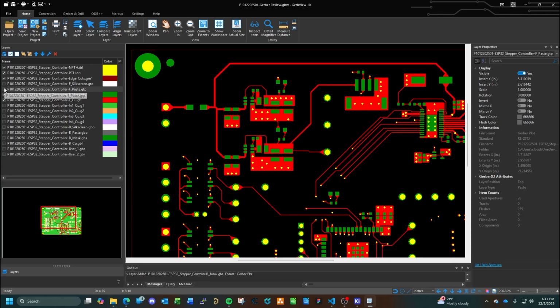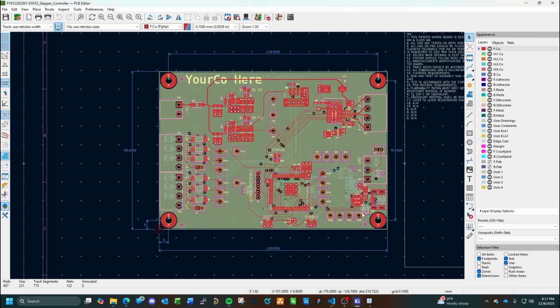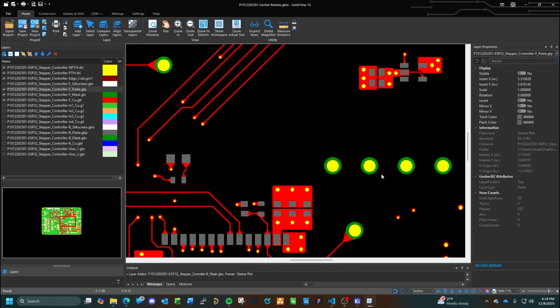And then they line up: your pad, your openings, and the paste, they line up. You can stack them together. That's basically what you're looking for. And that your through-hole parts don't get pasted, but they're still opened up because they're going to be plated through-hole. They're actually pads that you can solder to. So like this will be a solder pad that you run the through-hole part to and actually solder to. So you want to make sure the solder mask is open around that.